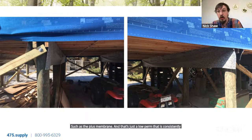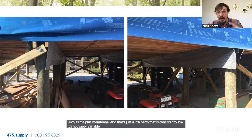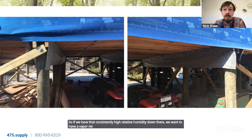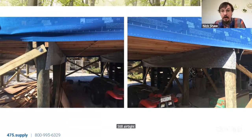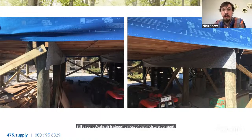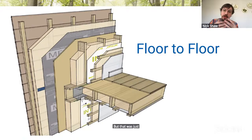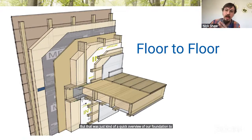And that's just a low perm that is consistently low. It's not vapor variable. So if we have that consistently high relative humidity down there, we want to have a vapor retarder on the underside of that floor system, still airtight. Again, air is stopping most of that moisture transport. Air that is really wet is where most of our moisture is coming from. But that was just kind of a quick overview of our foundation to wall transition.